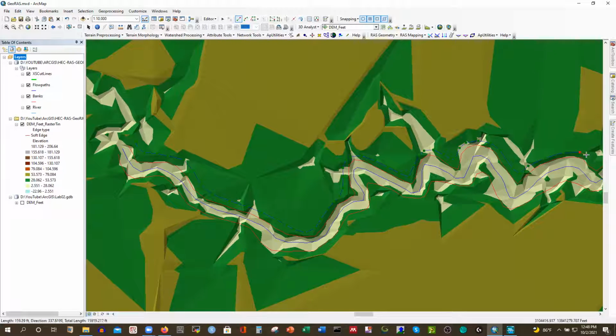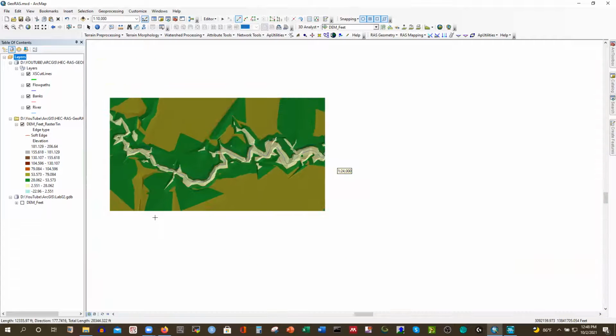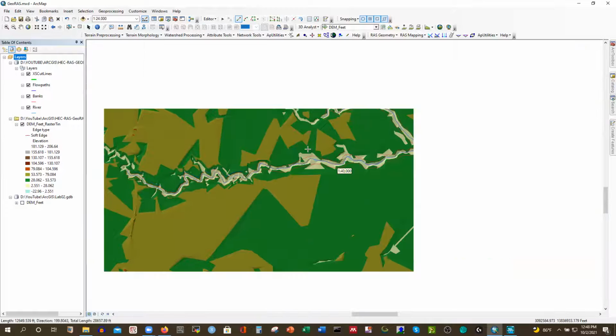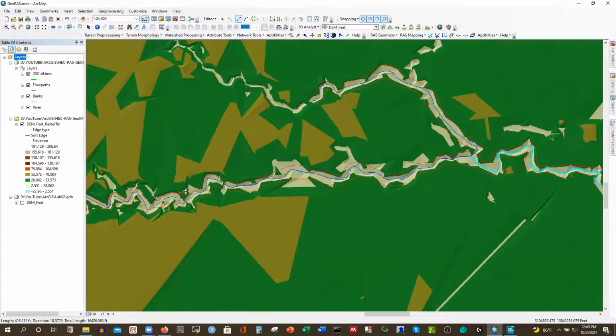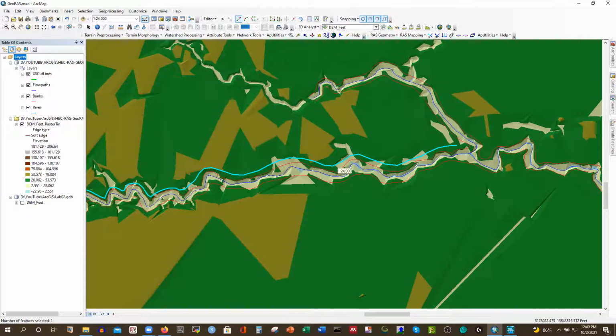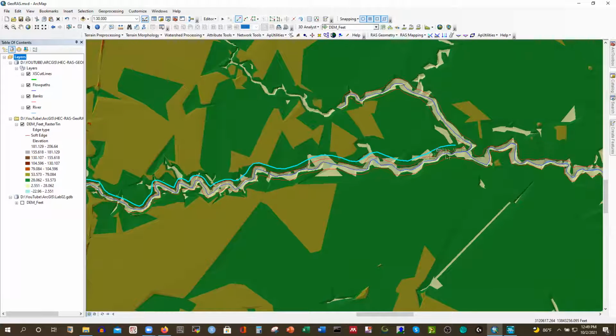don't suggest that one. And then you can use your trace tool to just quickly follow along, right? Generate your flow path, because in order to use that trace tool, you need to have the line right beforehand, then it will follow any line, any shapefile or anything. And if you have your bank line already digitized for any region, then you can use those. I'm gonna finish off here, okay, because I'll use the bank flow path line for the tributary.